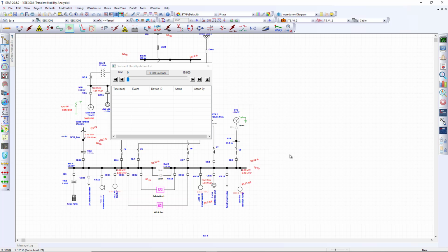Now, for our next example, we're going to perform a different type of study. Motor starting studies are essential in industrial power systems, as they serve several purposes, like, for example, voltage drop or voltage impact due to the starting of a motor, motor feeder sizing, starting acceleration time of the motor, or even the stability evaluation after a large motor is starting our system. And for each one of those purposes, ETAP offers a solution. However, today with the UDM Scope Plot View, we'll learn how we can combine all those solutions to make the analysis of the results even more efficient.